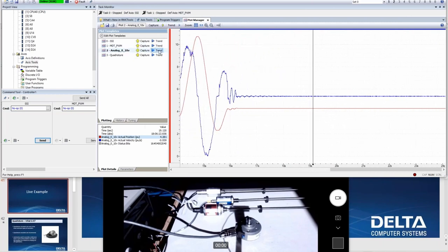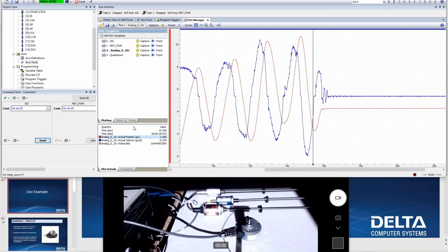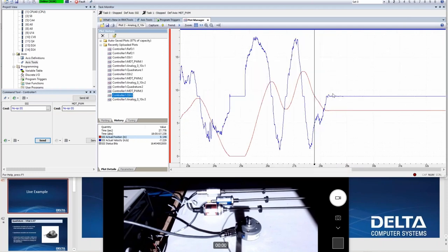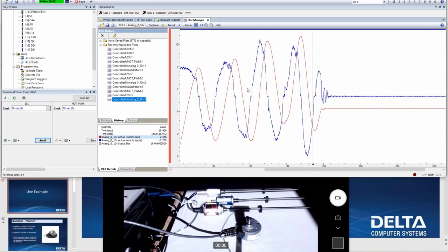And you really have to dive into the details, and it's very difficult to see with your eye that you're going to be able to control a much more precise system with the SSI versus the analog, because this analog plot looks very similar to my SSI plot here. You can't really see a whole lot of difference, but there actually is quite a great deal. And if we were to really zoom in here, you'd see basically what looks like the difference between synchronous and asynchronous, right? Those plots that we were seeing at the very beginning of the webinar.